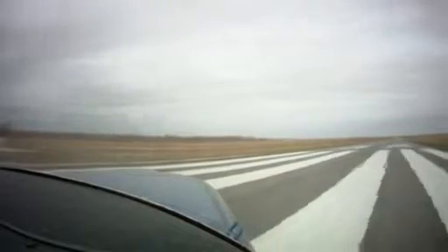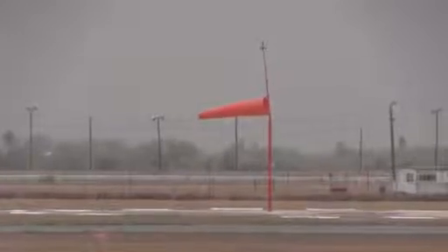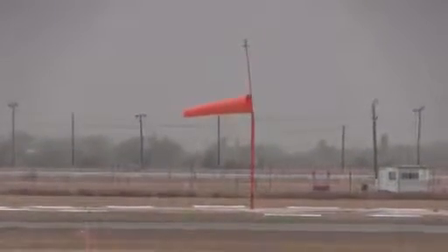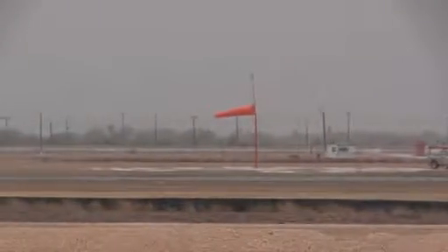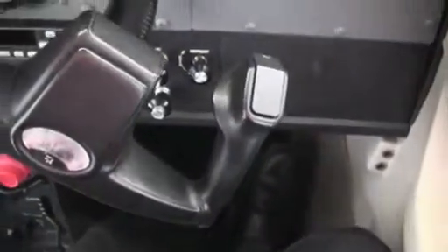As we taxi into the runway, it is essential that the windsock be checked so the crosswind condition may be recognized and anticipated. With this in mind, full aileron should be held into the wind as we start our takeoff roll. This crosswind correction should be held while the airplane is accelerating on the runway until the ailerons start becoming more effective. With the aileron held into the wind, the takeoff path must be held straight with the rudder.